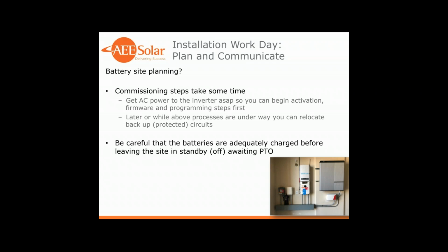So the point is to get that inverter connected, get the commissioning processes going, and it's actually really nice if you can get the battery charging as well before you finish for the day. That's a way to ensure that the system can stay in the off or standby position for quite a few weeks without causing issues to the battery or related hardware.